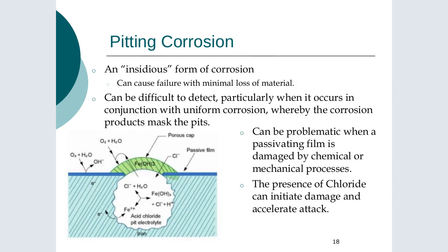And crevice corrosion is similar to that. So what happens, I'll summarize it here, is that we have a microenvironment, a microclimate, set up inside here that is really aggressive and not good for the material. And here we have a passive film. So due to this barrier here, we're getting a change in the mobility of ions going through. So we get a change in the local environment that gives us accelerated attack. And again, chloride ions here can be quite bad for this. Okay, so again, pay attention to what may be in the environment or may arise in the environment in future.